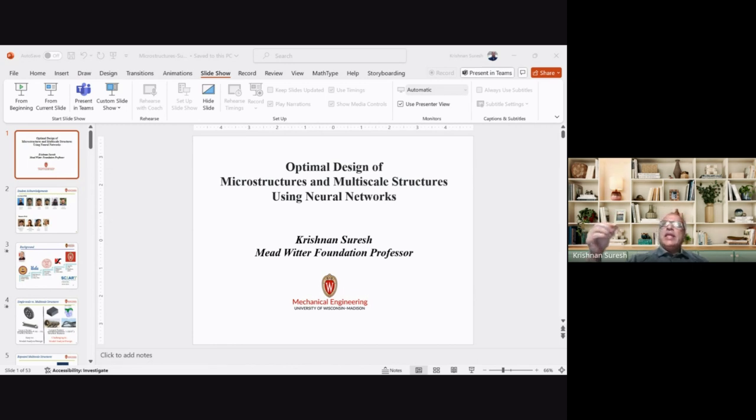And the key idea, and again, some of you may be familiar with it, some of you may not be, is homogenization, which is what I'm going to talk about. Homogenization is very, very simple. It's almost like saying, what is the equivalent behavior? I don't want to know the details of all the things that are going on at the microstructure, but I want to just use the basic behavior of that and use that in a broader context. That's called homogenization. You create an equivalent behavior, and that's called the homogenized elasticity tensor.